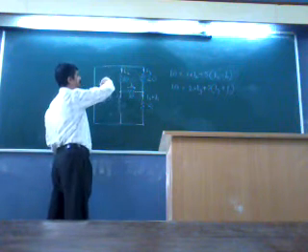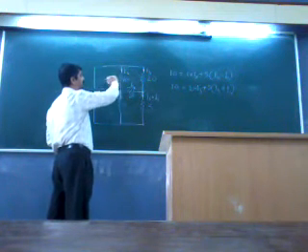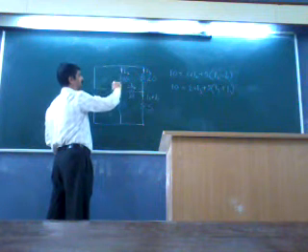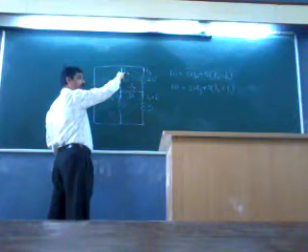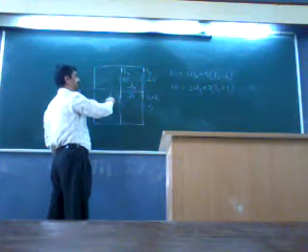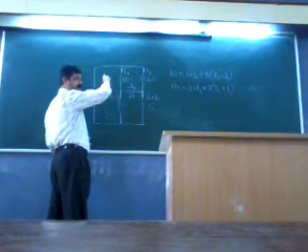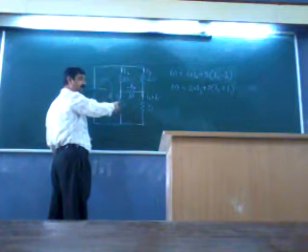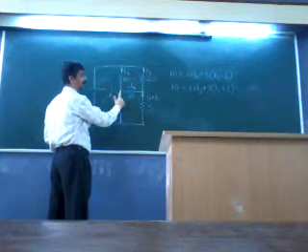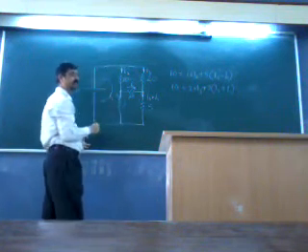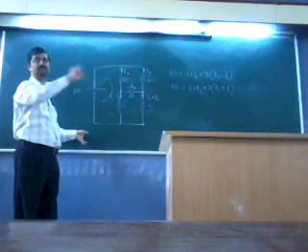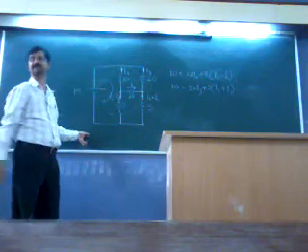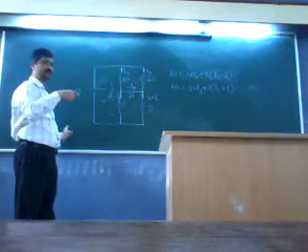And when you are traveling in a particular direction, if you are traveling in the direction of the current, you take this drop as positive. So 10I2 you directly take. 5 into I2 minus I1 you directly take. Even the reverse means if the current is flowing like this and you are traveling like this, then drop you consider as negative. So voltage source equal to voltage drop. Or algebraic the voltage across the loop is 0.